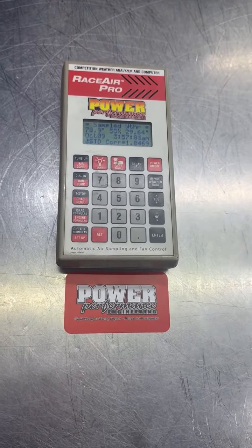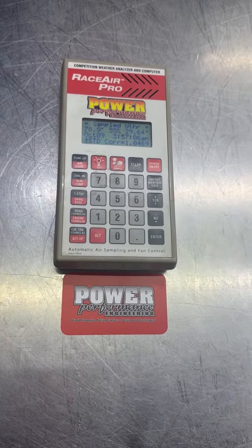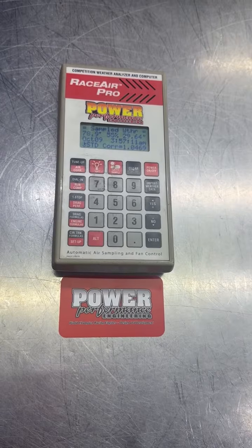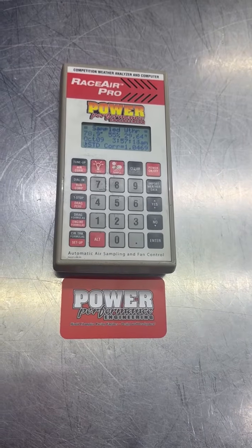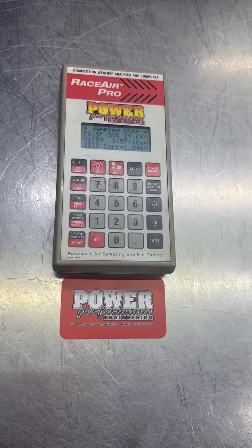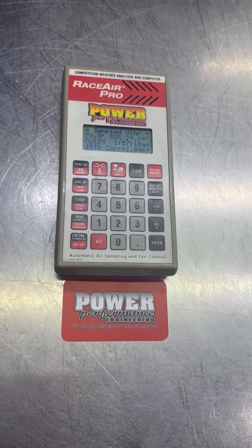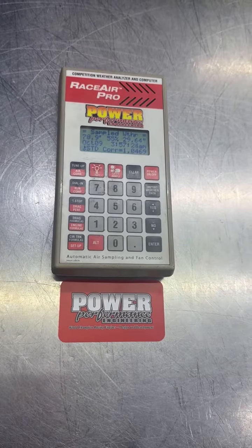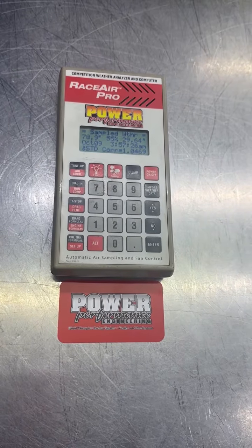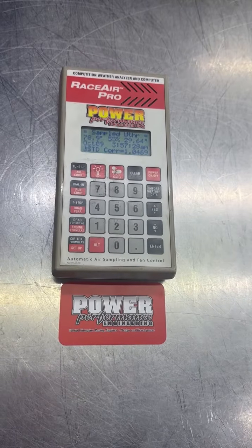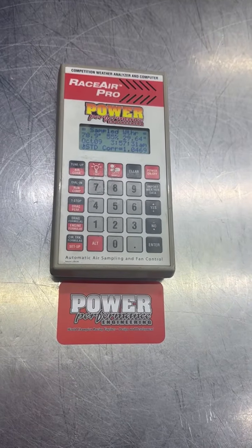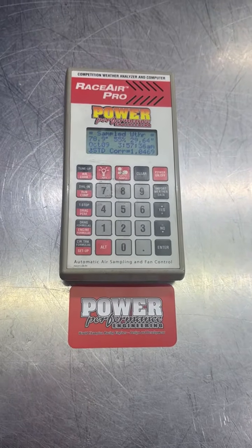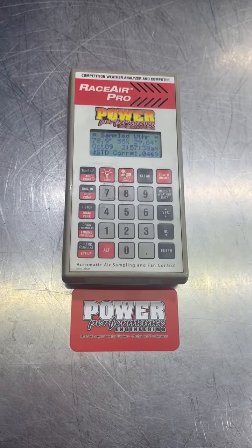Anyway, today we're going to talk about weather stations and how we use them in our race programs and what they're for. This here is a weather sampling meter. We're measuring all the air parameters, and we come up with a correction factor, which is typically the J1349 Society of Automotive Engineers standard, referenced by all manufacturers to rate horsepower. In other words, you can rate the horsepower under different atmospheric conditions based on current dyno numbers.